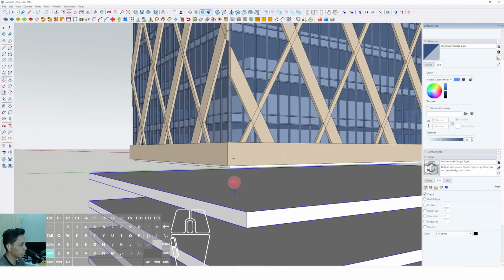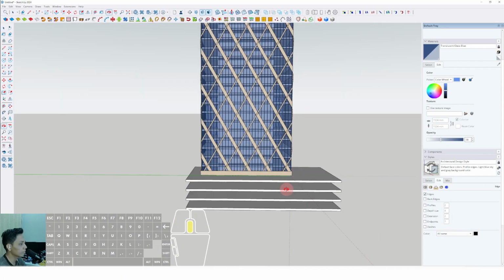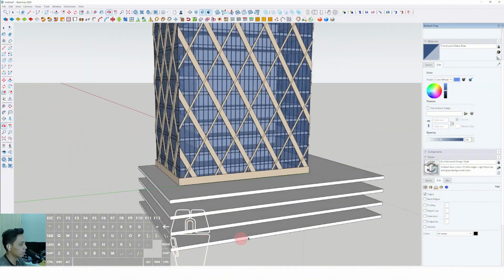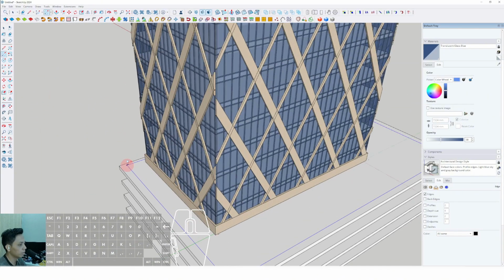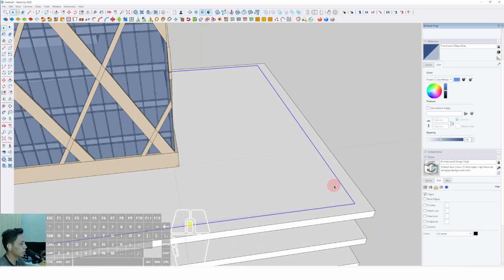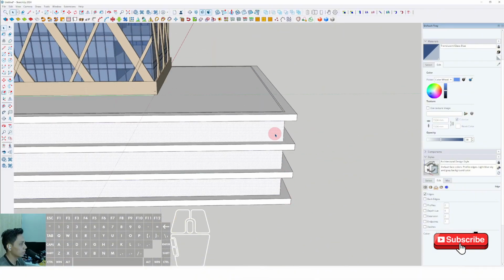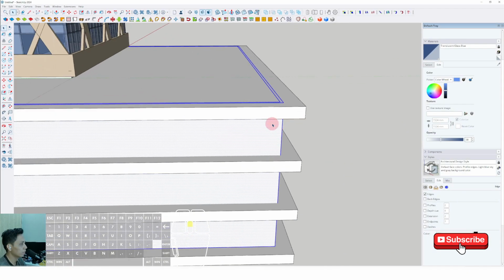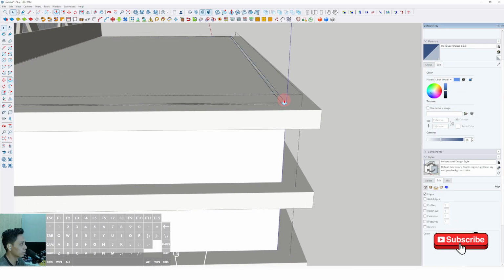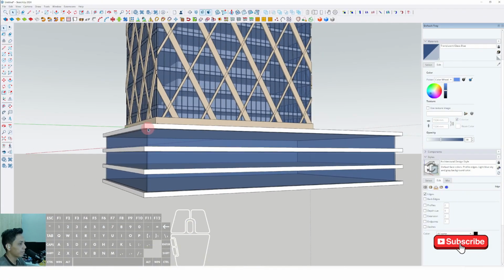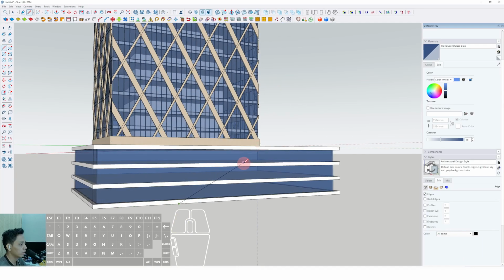Okay, then you can select move, place to this position. And you can add the glazing here with any size and position. This is just for example, so you can adjust this one. You can adjust it and improve it to more details. Okay, we have to make group, then we have to push it down to this position and select the glazing and click from this corner to this corner.